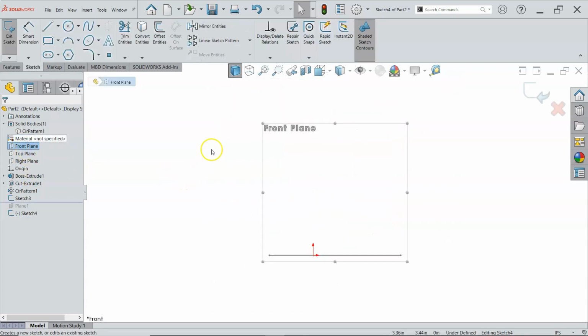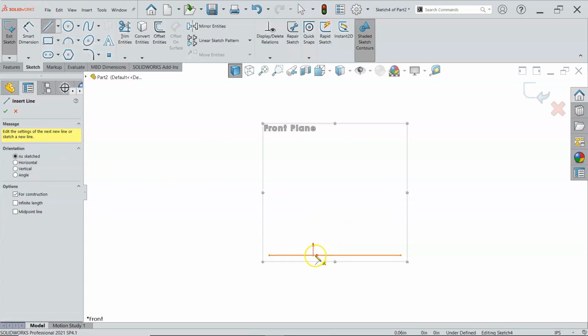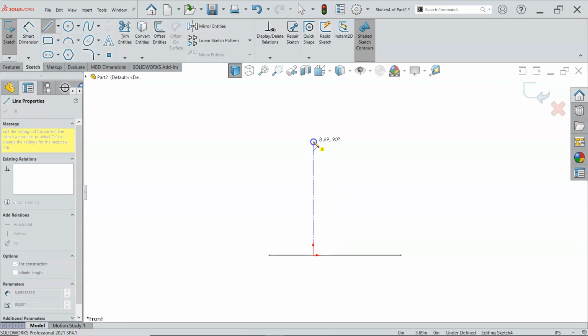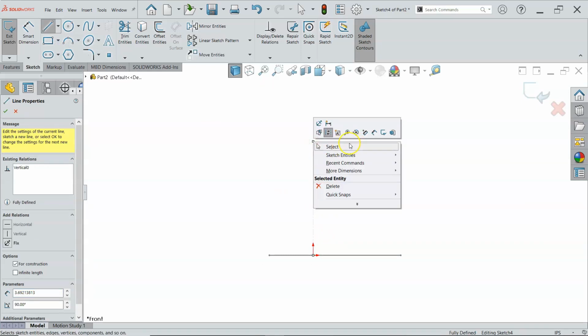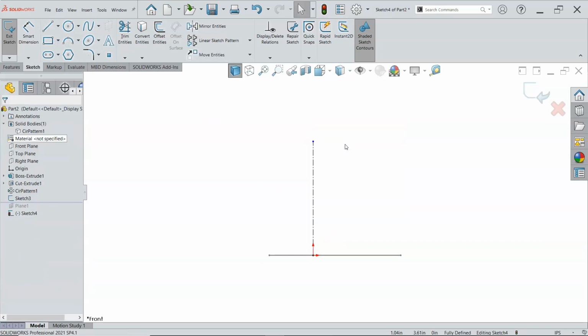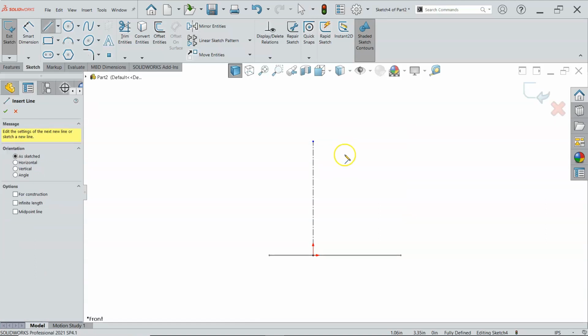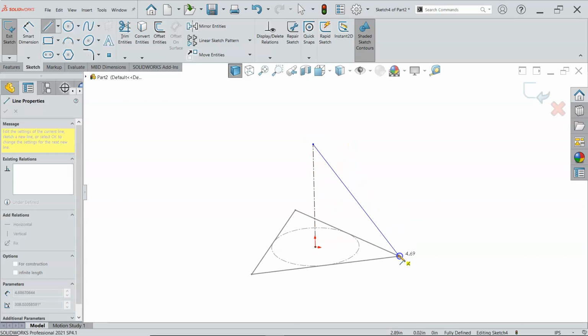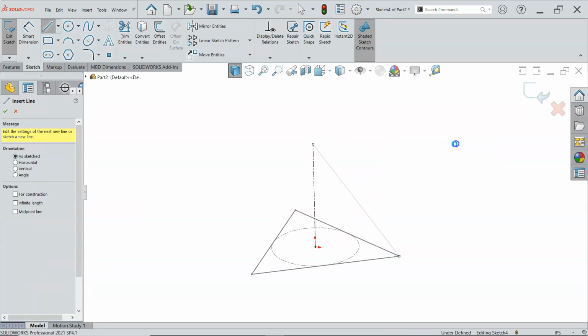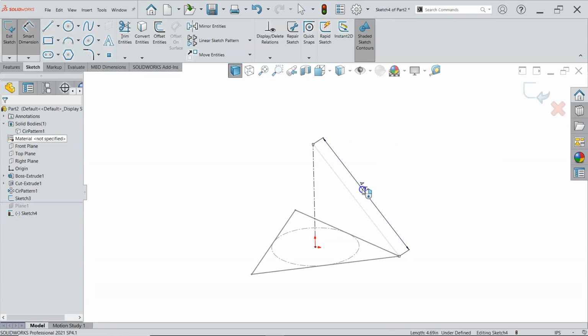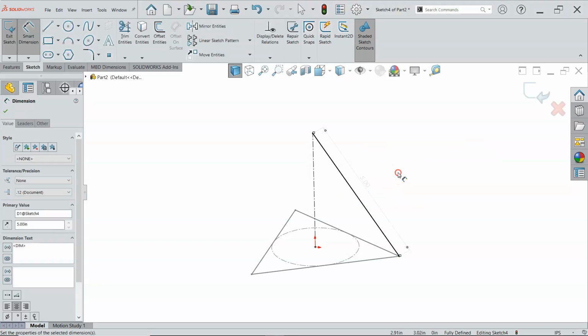Make sure I get it this time. I need, we'll go with the center line. Center line's helpful. I don't necessarily have to have it, but it does come in handy. And then now's the time to start using some of the shortcut keys, L on the keyboard. And I'll just look and make sure that those are going coincident. And then I can set a distance of 5 inches.